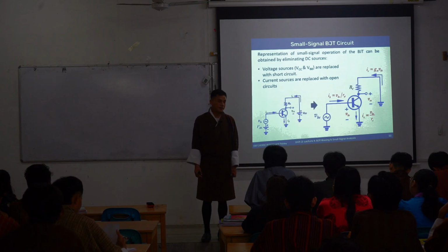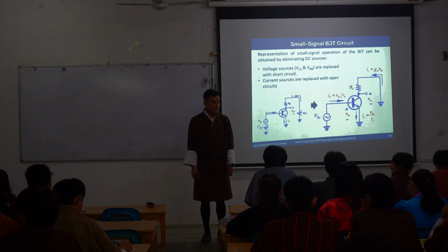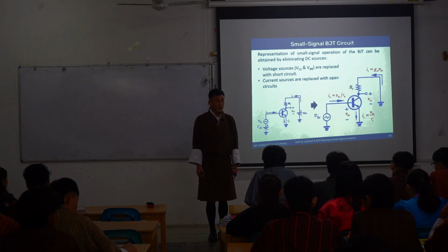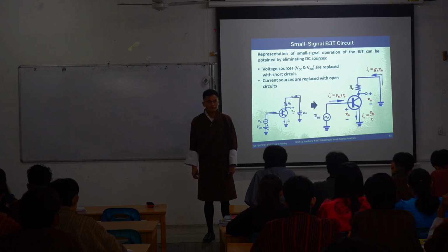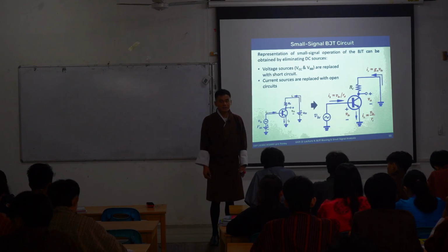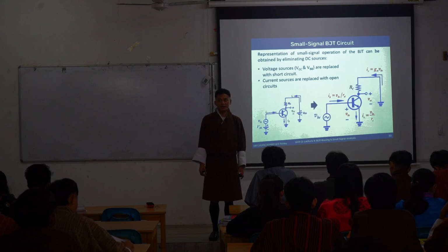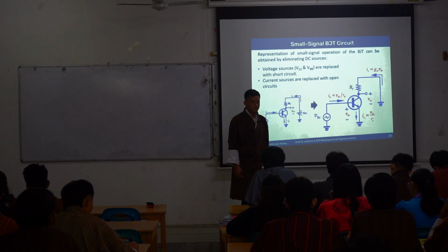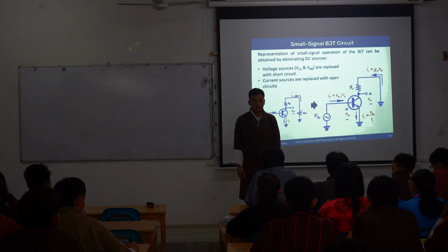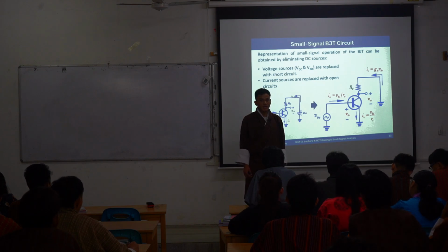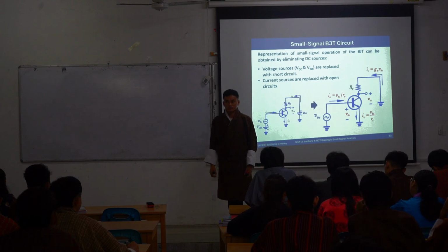What's the formula for ib? That gives r pi, VB by IB. If you simplify that, what you will get? Beta by gm. 1 plus beta times ib is your re.